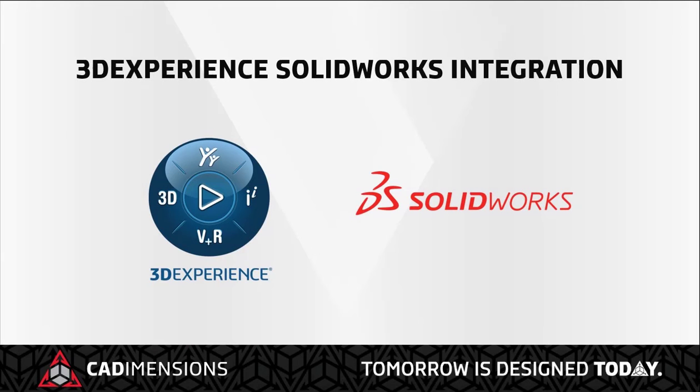In this video, I'm going to explain what the 3D Experience integration is, what it changes, and how to activate or deactivate the setting. With SOLIDWORKS Desktop and SOLIDWORKS Connected, there's an option that can be turned on to automatically create and convert files for compatibility with the 3D Experience platform when you open them. This option is the 3D Experience integration, and it changes a few notable things that you'll want to be aware of before you decide to enable it.